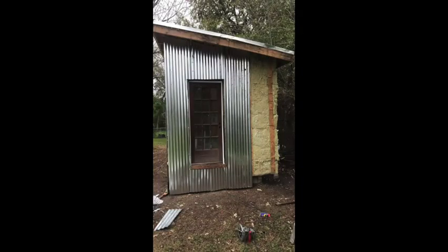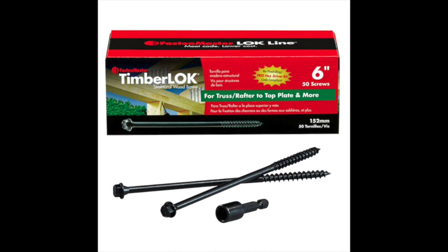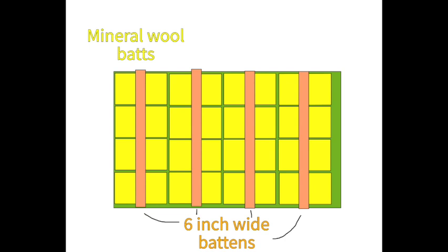As you can see, these screws run along a straight line here. And underneath here is a batten, which is basically just a strip of wood that you use with lag screws, which are really long screws. I use 6-inch long screws, and I was able to screw down the wooden battens, which are just strips of wood. It's plywood cut into 6-inch wide strips. The plywood's 8 foot long, but it's about 6 inches wide.